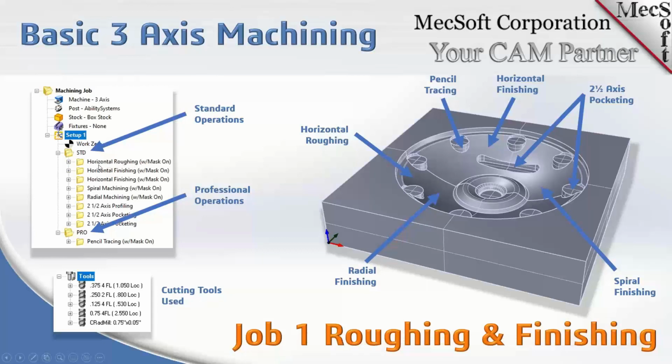So we'll have the masking surface on for both of the roughing and a horizontal finishing operation. And then we'll also do a spiral and a radial finishing operation. And then we're going to wrap it up with the profiling around the perimeter. We're going to pocket out the pockets, and actually the areas on top of these bosses, I've decided to treat as a pocket, which turned out pretty well, rather than a face.